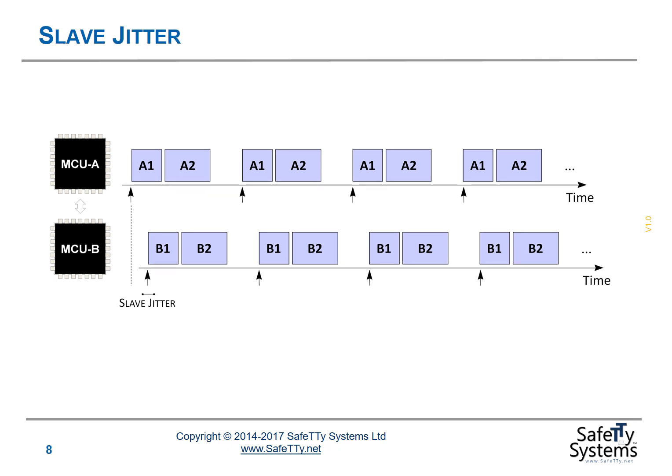Slave jitter arises through a similar source. So slave jitter refers to the variation in the timing of the ticks on the slave relative to the timing of the ticks on the master in such a design. So this might arise, for example, if there was any variation in the transmission times of messages between MCU A and MCU B.